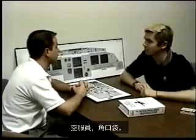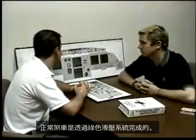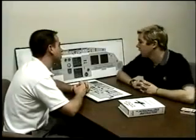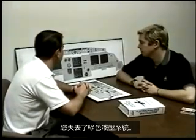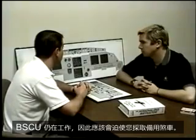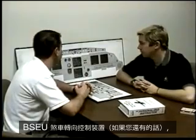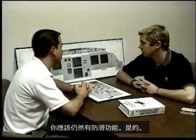Normal brakes is done through the green hydraulic system. What would occur if you lost green hydraulic system? I'd lose normal brakes. You've lost green hydraulic system. The BSCUs are still working, so that should force you into alternate brakes. Correct. BSCU, brake steering control unit, provided you had that still available, you should still have anti-skid.